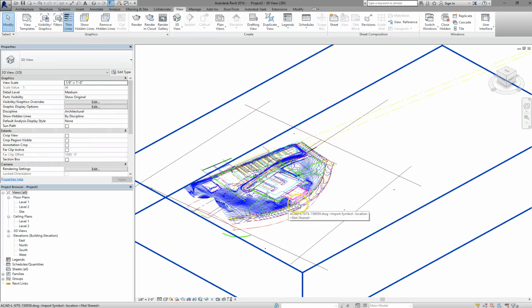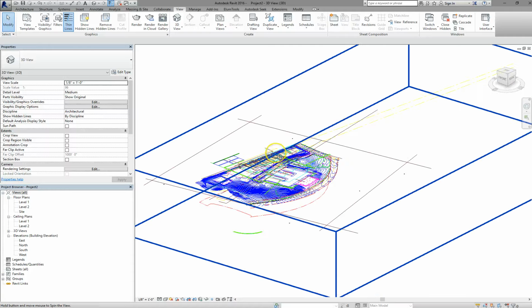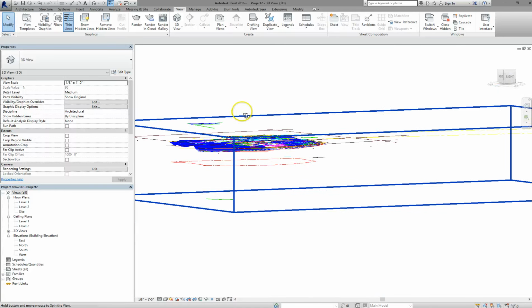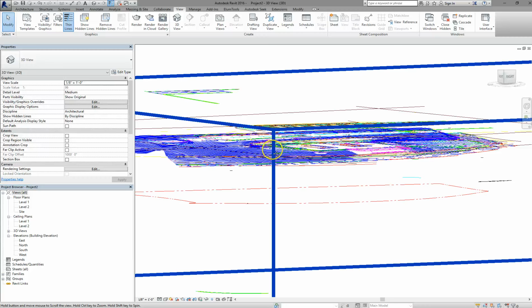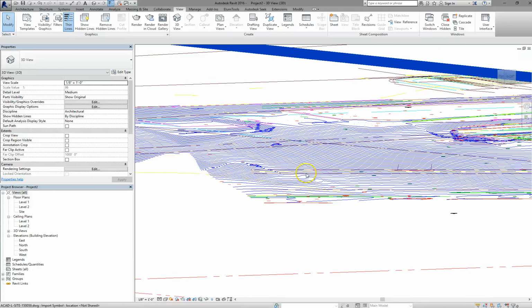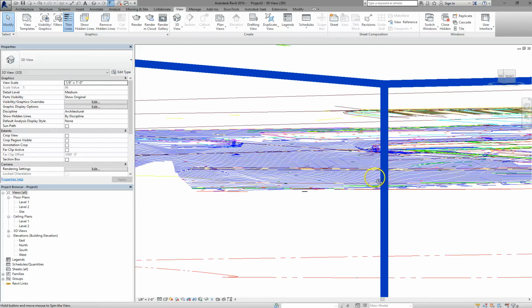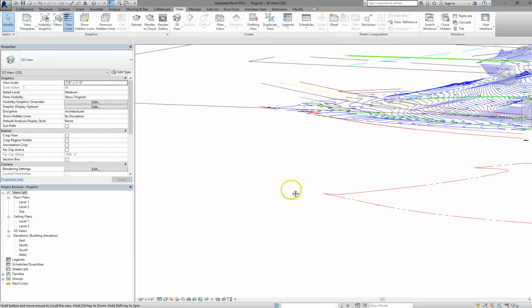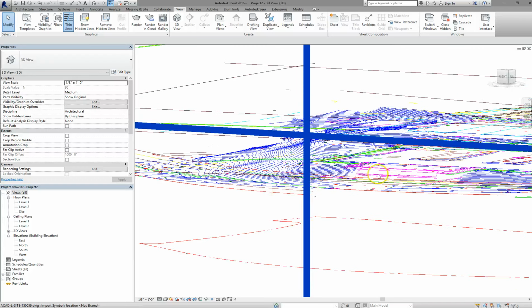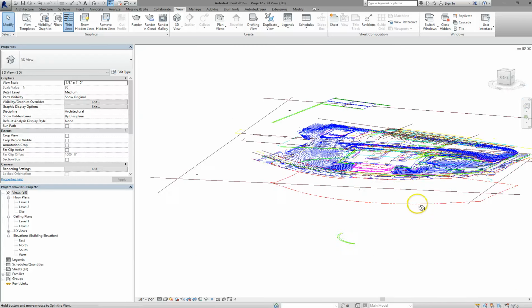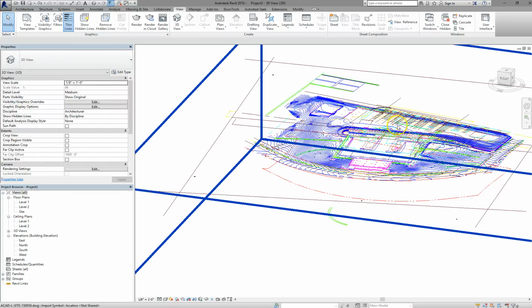If you hold down the Shift button and push in the scroll wheel of your mouse, you can rotate the file. And you'll see that what happened is this AutoCAD file, and the way that the civil engineers surveyed this, is it has 3-dimensional contours. So you can see my contours are in 3D. This is very, very handy when it comes to making your topography.